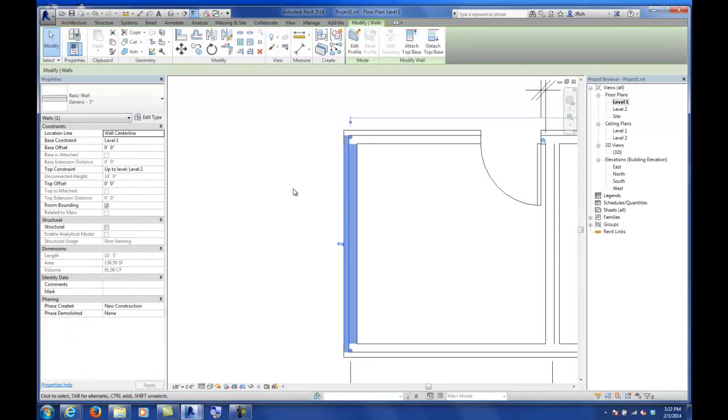So actually, I would echo that completely, in that there are a lot of default wall types in Revit. But as an architect, you're responsible for knowing what the construction assembly is to meet local codes for, I don't know, insulation or fireproofing, etc. While those are handy for sketching, I think in this studio and probably in general, following that logic is super important. Start with a default wall type, and then as you move through your project, you can edit the assembly layers based on what you know in terms of code and what the requirements are as you build them. Don't rely on the software to produce the wall assembly that's required for your structure. Okay.